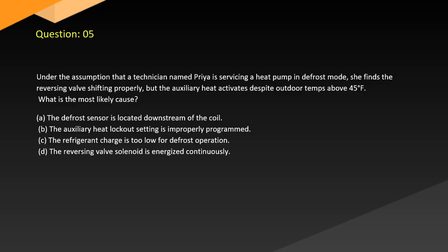A. The defrost sensor is located downstream of the coil. B. The auxiliary heat lockout setting is improperly programmed. C. The refrigerant charge is too low for defrost operation. D. The reversing valve solenoid is energized continuously.